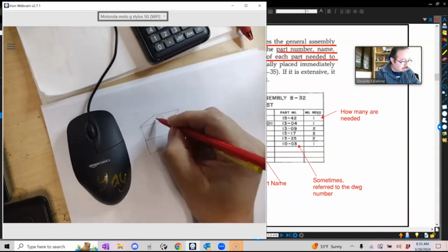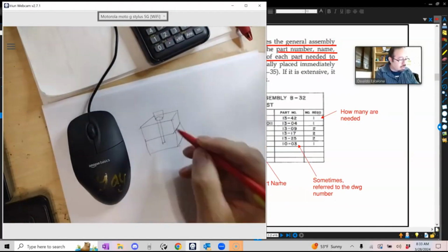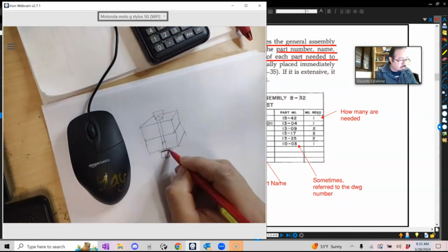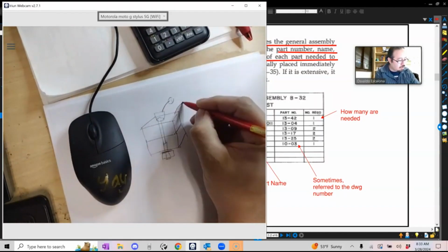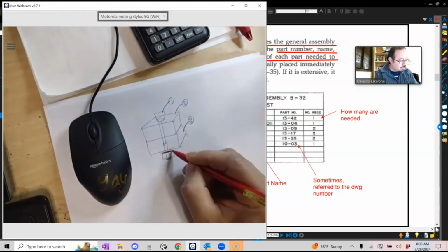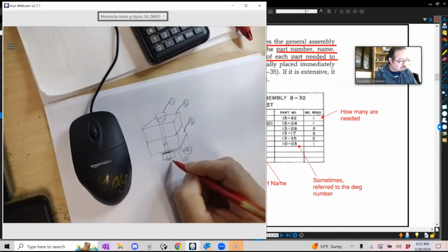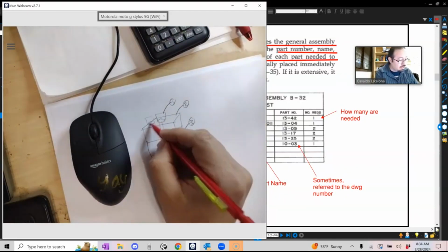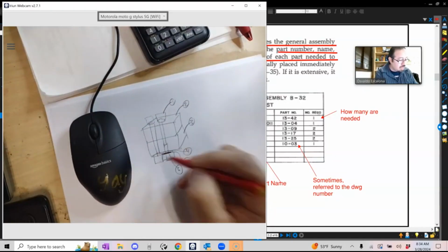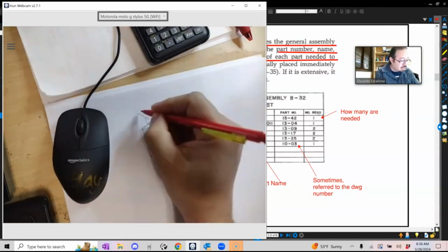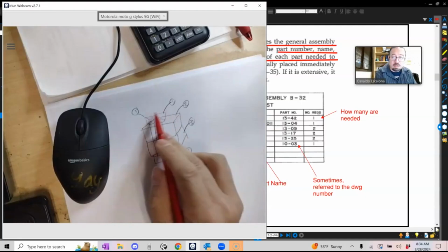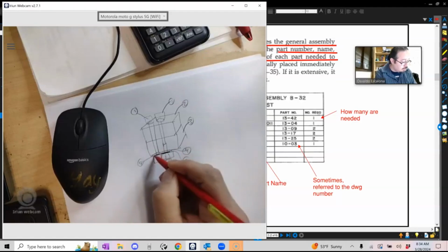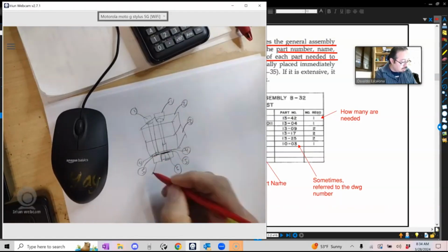And within it, I have a bolt. Right? And maybe on the bolt, I have a washer and I have a nut. Maybe here I have a lock nut in the middle. Okay. So I got 1, 2, 3, 4, 5, 6. 6 parts. Now, if I were to have another bolt right next to it, I can call it again, and this one will be 1 because it's the same one. You've got the 2 bolts. I want to call this one the washer. I'm going to call it 4. The lock nut, I'm going to call it 5, and the nut, I'm going to call it 6.